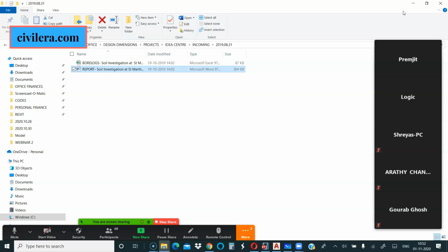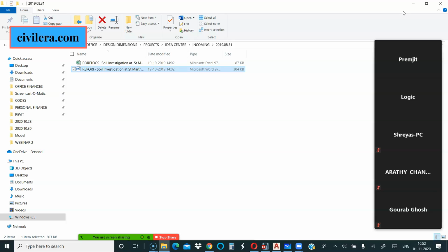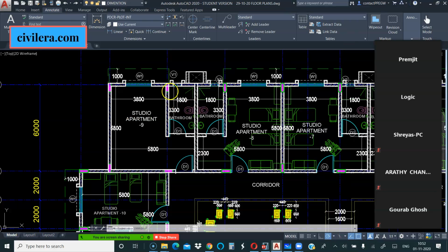So with this medium kind of soil, 18 tons, 180 kilonewton per meter square is not bad for a 3-floor or 2-floor building. You can have wider column spacing, not too wide, maybe 5 to 5.5 or 6 meters. That's not going to be a problem. So that's how you start scheming.